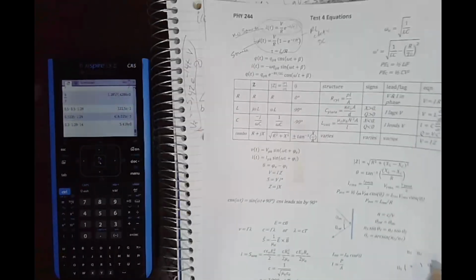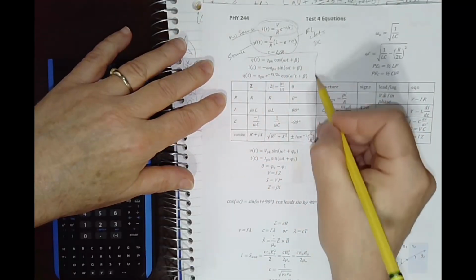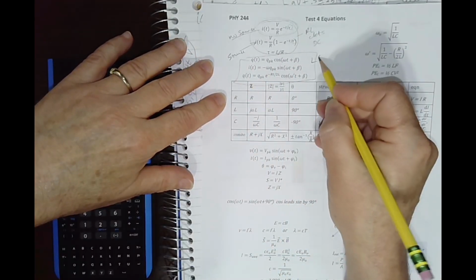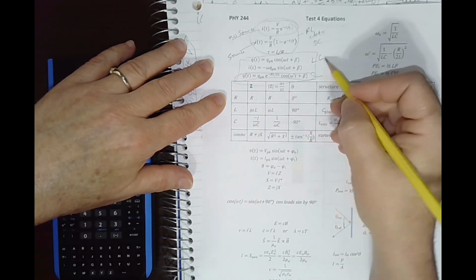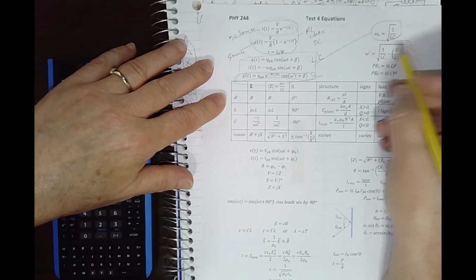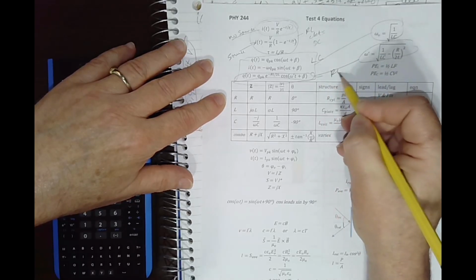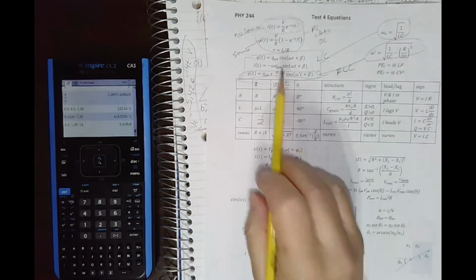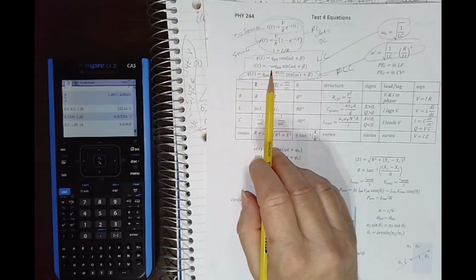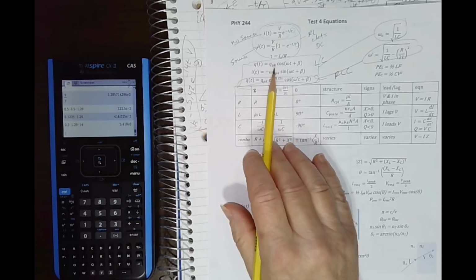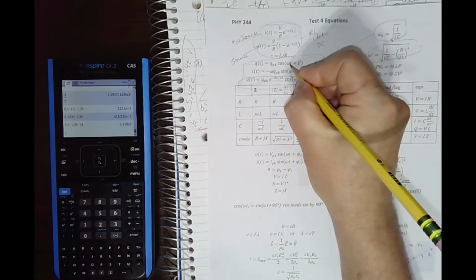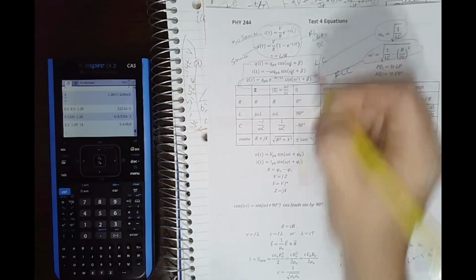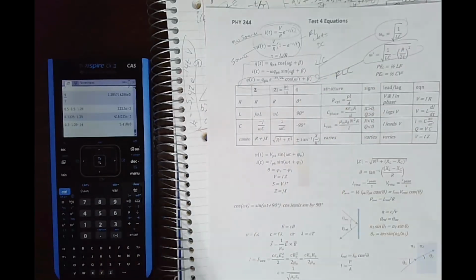And so that's where we get into this set of equations on our equation sheet. This is for an LC circuit, and this bottom one is also for the LC circuit. And this bottom one is for an RLC circuit, where we're actually going to have some resistance. And so just looking at what happens, when we have the circuit, do the differential equation, solve it, we get sine wave kind of things, and maybe we should put omega naught on this for now, because we're talking about just the LC circuit.